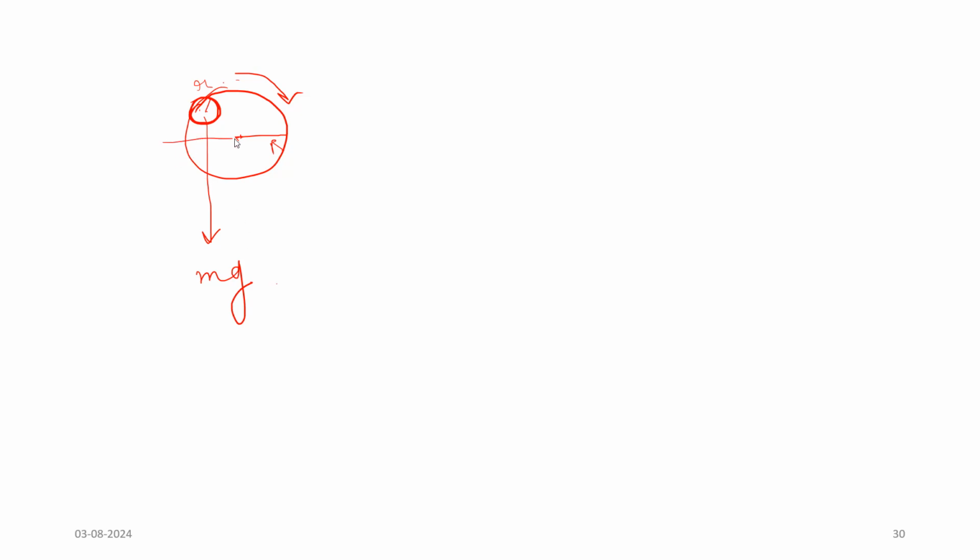And this is the ball, and it is at an angle with the center of the ball. The feed particle is at an angle with the center of the ball, which is theta. Now the ball will rotate at a speed and it will gain some speed, which produces the centrifugal force.